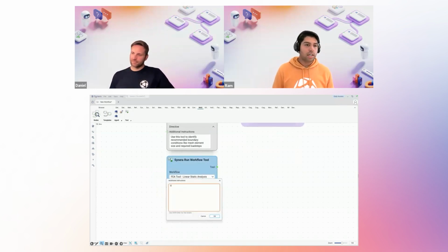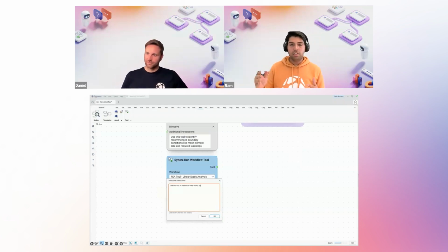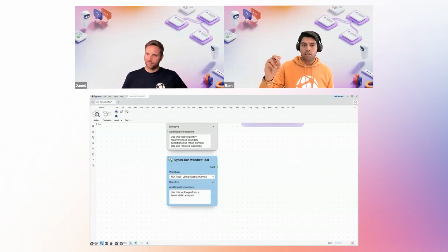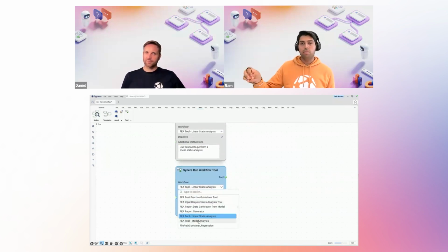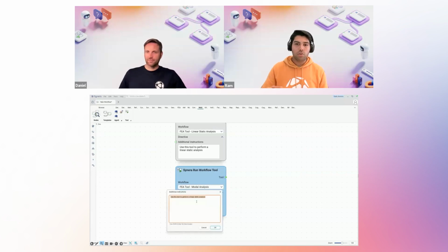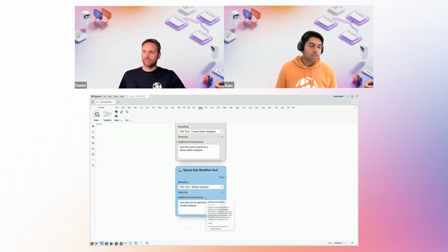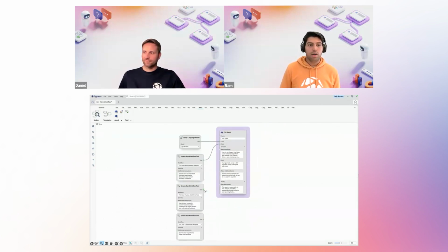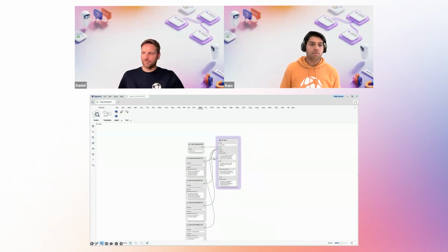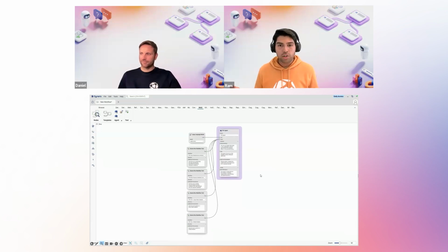And in the same way, I also attach all the other FEA tools we created. And this is the linear static analysis. And again, a simple instruction when to use this. So a pattern is we use a tool, we just add a simple hint when to use this tool to an agent. And Synera takes care in the background how to interface with all these tools and easily connect them to an agent. And now I'm almost done setting up all my tools, and I want to just connect them to the one agent. So this agent now finally has 4 different tools, LLM, it has an instruction, and now it's ready to go basically.